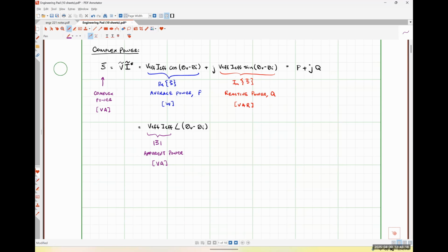And then I would compute my apparent power needs for the whole system and then solve for that effective current. And that effective current is going to tell me what size of the conductors I need to use to implement that power system. And I'll have you do that in a couple of your homeworks, and you'll be looking at some portions of the National Electrical Code, the NEC code, particularly the ampacity tables, in order to figure out what size of conductor to use.